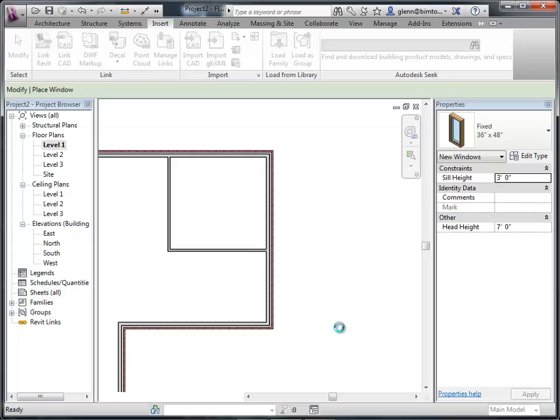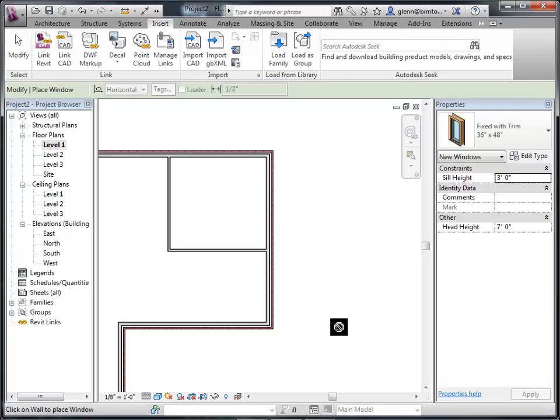But I'm not too worried about a couple different sorts of windows. What you don't want to do, and watch out for this when we start doing structural elements, is load in the entire steel library. You've got hundreds of different elements there, and that'll really bog things down. But in general, a couple windows here and there are not going to bother you.